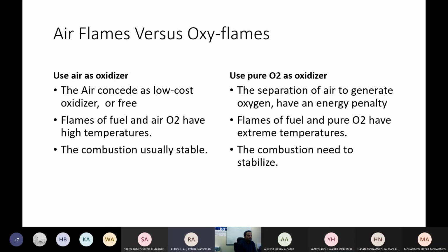Switching from air to oxy-combustion, however, entails a different degree of freedom for combustion operability. Air is an abundant low-cost oxidizer, so lean operation is typically used in air-fuel gas turbines to control the combustion exit temperature. The separation of oxygen from air, on the other hand, comes with an energy penalty, so oxy-fuel applications need to be operated near stoichiometry to utilize both the fuel and oxygen efficiently.